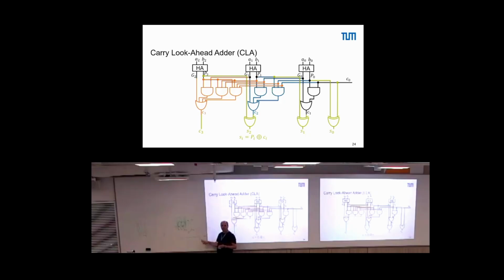So to DC actually nothing, but if I switch at the input once from 0 to 1, so let's say we have an arbitrary steep edge here, what would we receive here? So here you would receive effectively something like that. What happens if I increase the capacitor? Less steep. So if you increase the capacitor, you get less steep.